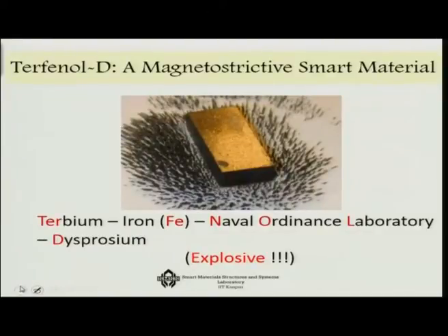The one which is mostly used is Terfenol-D, and as you can see, the name itself tells us its composition. There is Fe, which is the iron, then Ter is the terbium part, so it is a terbium iron compound to begin with, and NOL is nothing but the Naval Ordnance Laboratory of the USA, who are credited as the first people to discover it, and D is the dysprosium. That's how the Terfenol-D name appears.